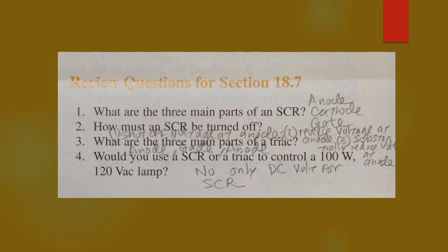Question 4. How would you use an SCR or a triac to control a 100 watt 120 VAC lamp? The question again is, would you use an SCR or a triac to control a 100 watt 120 volts AC lamp? And you would have to use a triac since it is the only device that can handle AC of the two.